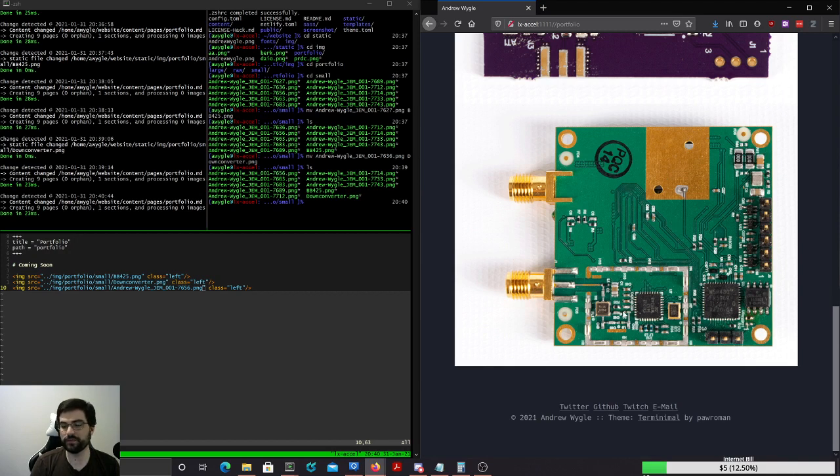Okay, so this is the flight configuration of my Elysium VHF UHF radio. I'm actually really proud of this design. This is a CubeSat radio, and the goal for this thing was essentially very power efficient communication. And to that end, it's capable of 25 milliwatt idle receive power and 50% efficiency on transmit up to 5 watts. Both of which are basically, the receiver in particular is an order of magnitude lower power than anything else that I've seen before or since. And I'm really happy with this project and how it came together.